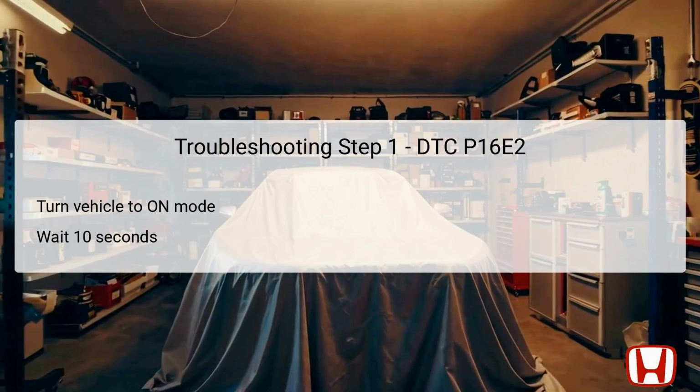It is essential to ensure that all components connected to the LIN are in their proper positions during this process. By performing this simple but crucial step, any temporary glitches that might cause communication issues can often be resolved before more in-depth diagnostic work is required. After waiting, the next steps would involve checking for any stored DTCs that could provide further insight into the issue's root cause.